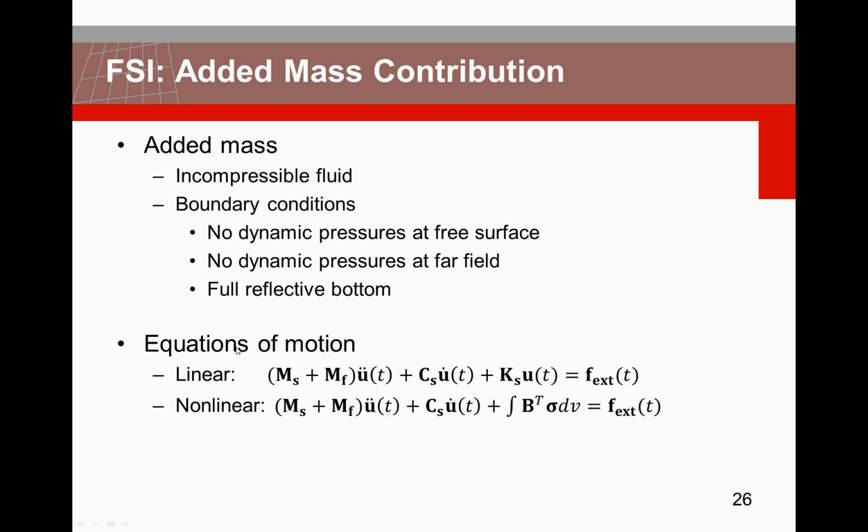In the equations of motion, what we then will get is the mass of the structure plus the added mass of the fluid. So that's actually not the entire mass of the reservoir that you have modeled, or the fluid part that you modeled, but it's only the part that is dynamically adding mass to the equation of motion. So that can be just a few meters of water from your dam, and the amount of mass from the fluid is being calculated with this method.